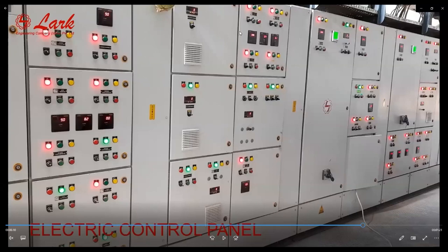So if the power consumption is on a higher side, which section do you have to look at, either grinding or pelleting, or where do we have to focus? To monitor the power consumption comparison, we are supplying separate energy consumption meters in batching, grinding, and pelleting process, as 80 to 85% of power is consumed by the pelleting and the grinding process.